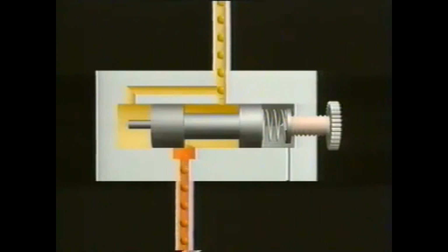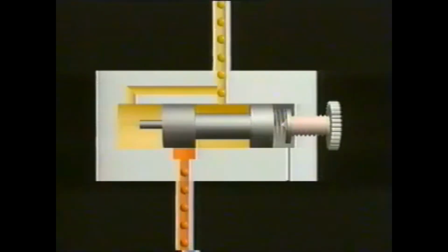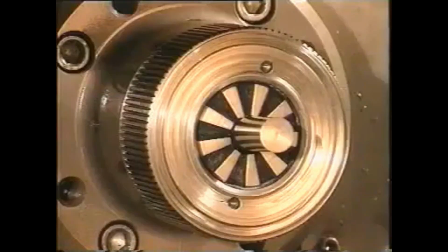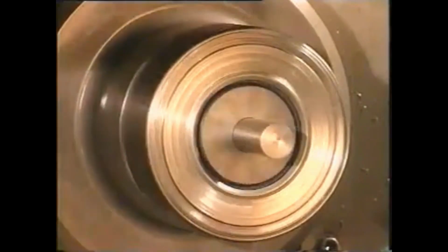Under certain conditions, this could happen while the piston is still moving in the cylinder. When the piston has reached its end position, the pressure continues to rise. This has the effect of the pilot piston closing off the pressure line completely, making it impossible to exceed the value set at the pressure regulator. This is a two-way pressure regulator. Its job is to limit the clamping pressure of this drill chuck to a predetermined value.